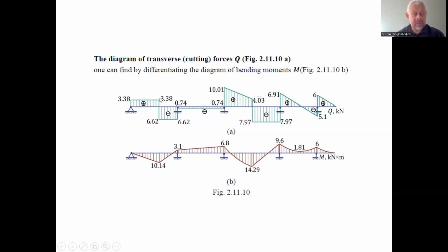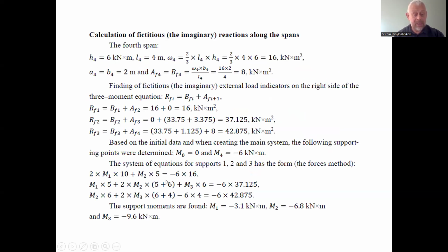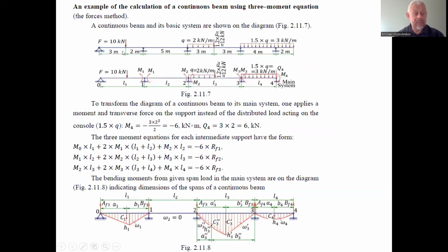It corresponds to the positive derivative, which is 10.14, and the magnitude of this evenly distributed shearing force diagram is 10.14 divided by the length of this part, 3 meters, starting right to left after the point of action of this concentrated force of 10 kilonewtons.